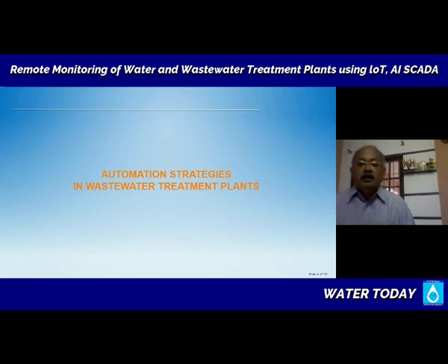Something like US EPA, Environment Protection Agency, there are some regulations and guidelines for what is the type of monitoring required. They could be used as a guide. And if your water contains so and so too much of nitrates, for example, then it is good to monitor for nitrate, but you need not monitor for each and every parameter that is there. The idea is to draw the line between what you want to measure continuously and what you want to measure periodically. Now, the periodic measurement you can even do with, nowadays you get these portable sondes, which is a bunch of sensors which you can carry to site and dip in the manhole, and you can see what the various parameters are.